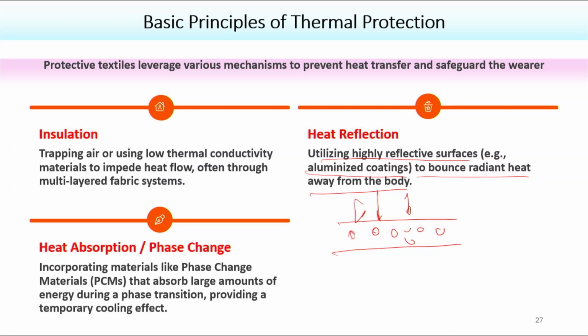Incorporation of phase change material absorbs a large amount of heat energy during the phase change, providing a temporary cooling effect. So, heat does not come inside. It absorbs heat, and then it acts as a heat blocker.